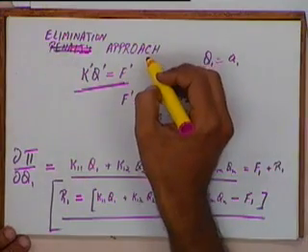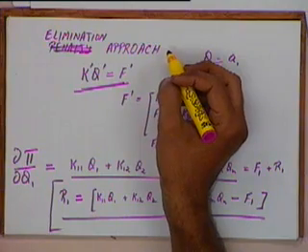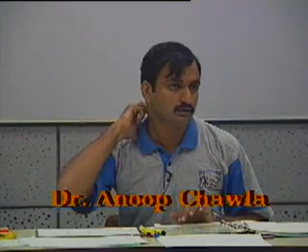Okay, this is in the elimination method. For multi-point boundary conditions, the elimination method cannot be used. Multi-point boundary conditions can be solved only by the penalty approach. Any questions with respect to either the elimination method or the penalty approach, and single point and multi-point boundary conditions? Okay, no more questions.